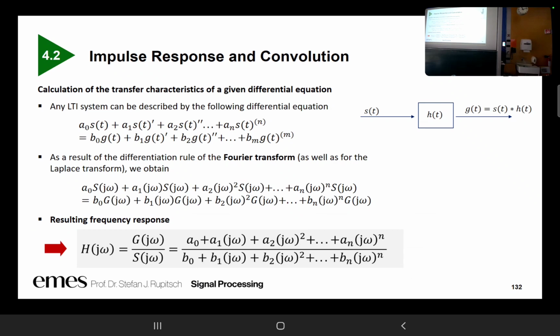Therefore, the derivative also has to be twice as large, and this is described with the multiplication by j omega. In case of an integration, the reverse behavior can be observed. The j is only the fact that the sine oscillation becomes a cosine, and cosine is a shift by 90 degrees, and the shift by 90 degrees resides in the multiplication by j. Okay? Fine.